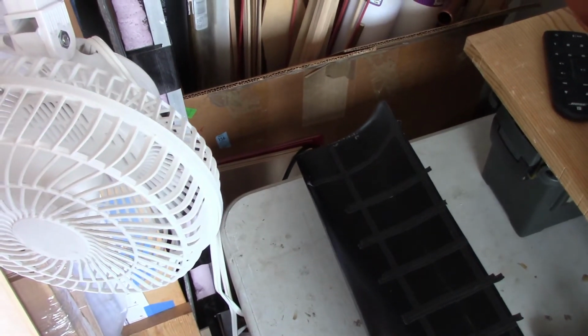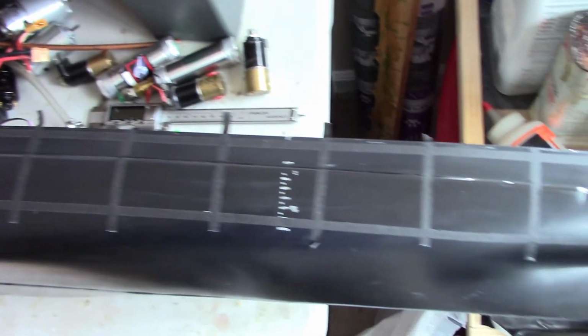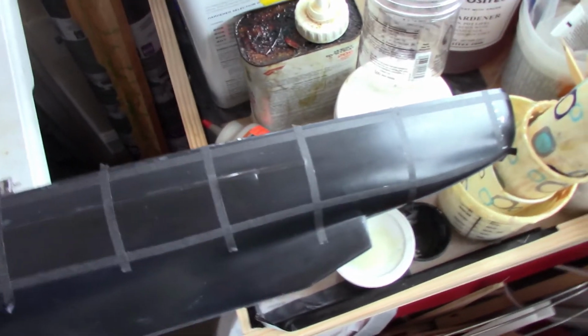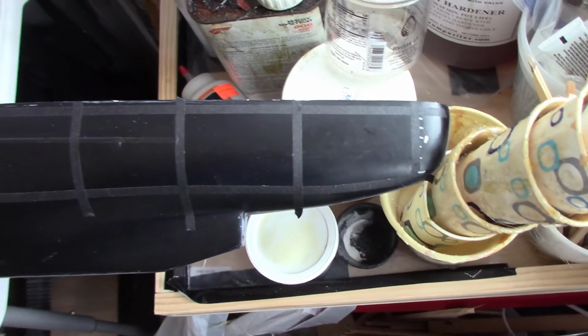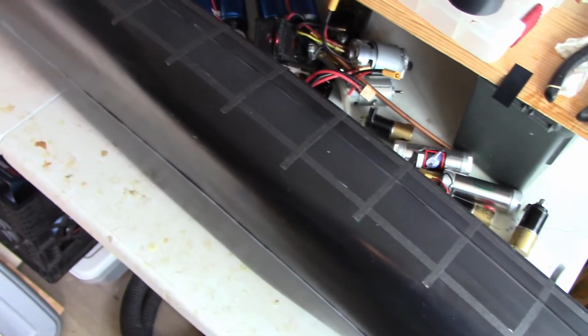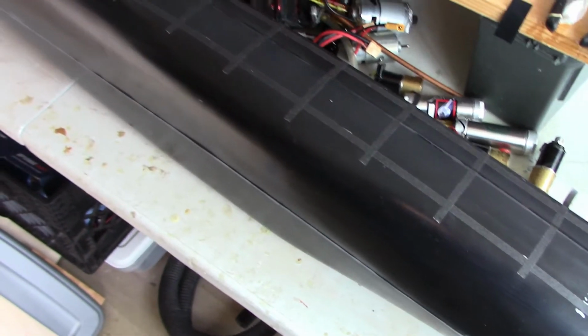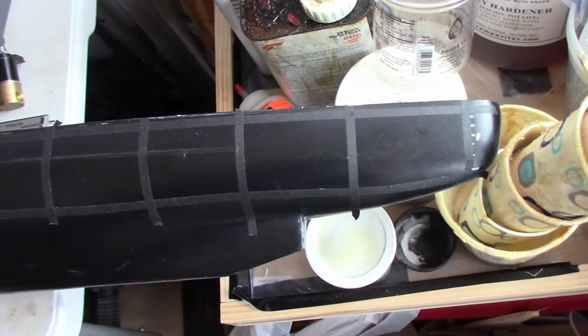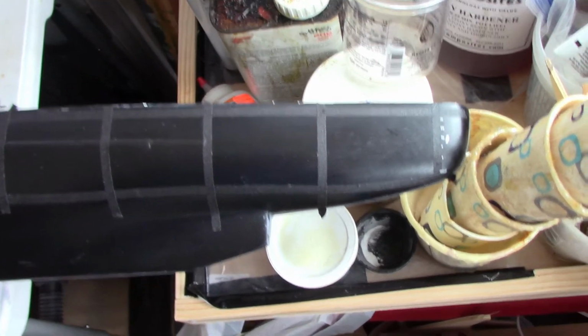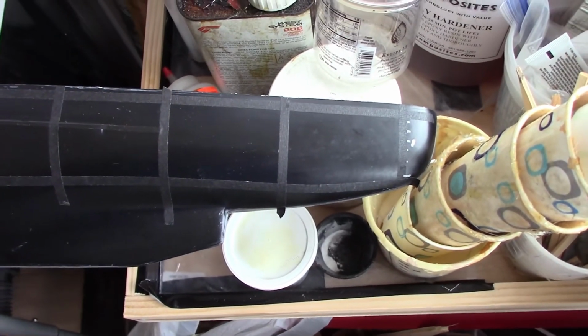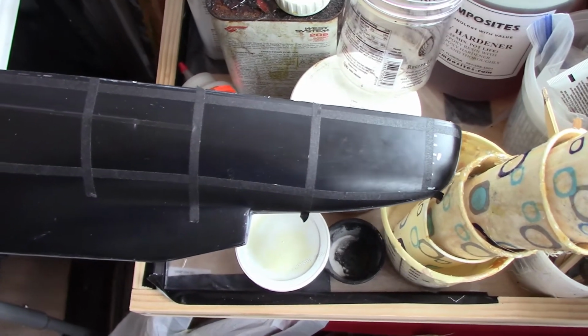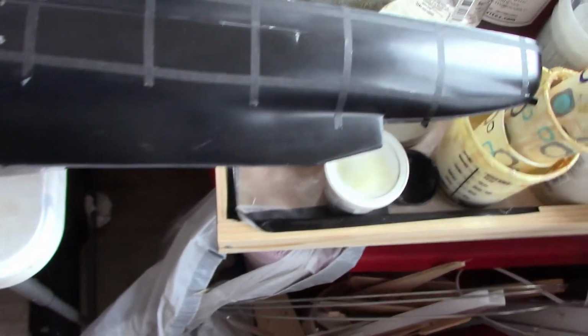So I got all the ribs marked out in tape. You can kind of see here. Nice even spacing. So just taking the dimensions I got from the spreadsheet, I measured out starting at the bow and went to the stern. You can kind of see in the stern that the last rib spaced out a little bit more, just kind of an accumulation of error down the length of the hull, but overall pretty minor.